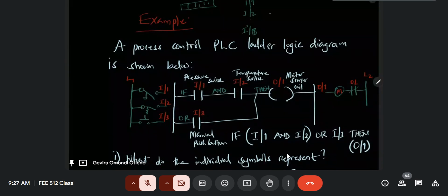Then from there, the outputs are now O1, O2, maybe up to O8. So you can find that a manufacturer decides the first memory location is called O0. Then the last one is O7. Okay. Or you can start from O1. Now that's manufacturer specific, but we still understand what it means. Some use Q for the output. So the output, instead of O, it's Q1, Q2, Q3.